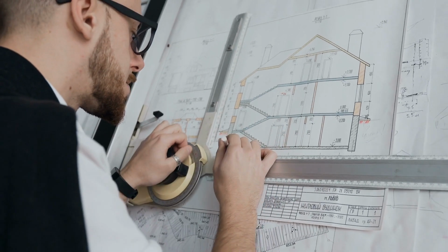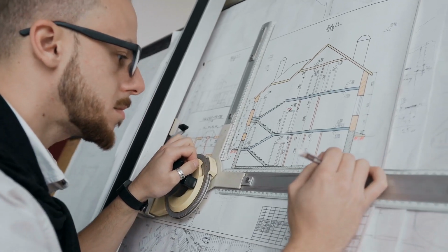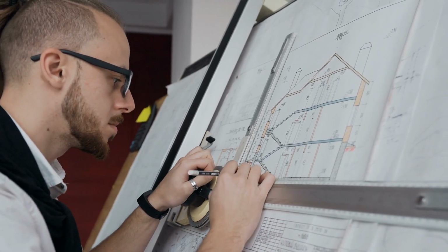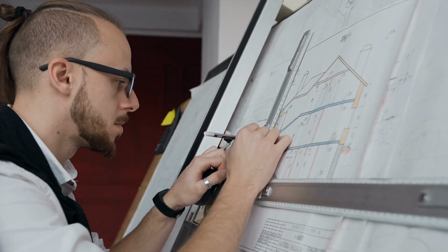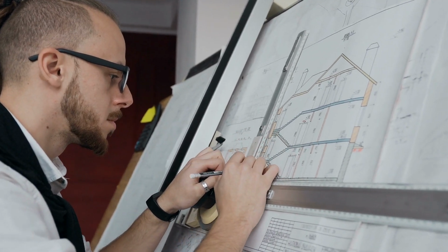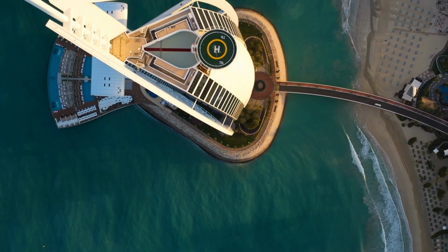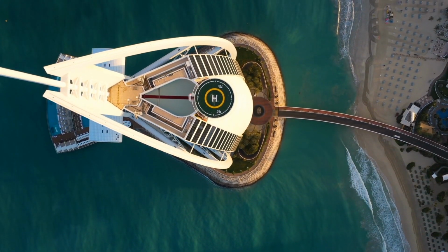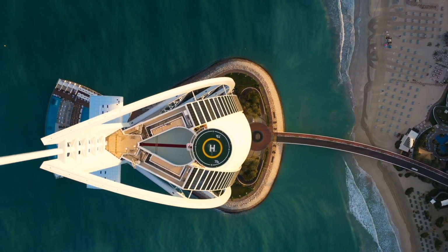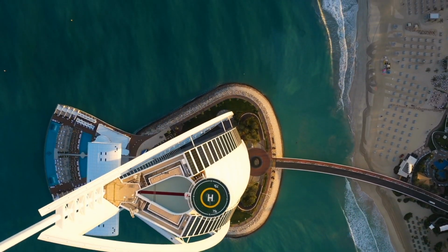Now that I've given you this overall information, it's time to dive into how we actually read construction drawings. I will be showing an example drawing soon that we'll look at in great detail, but before we do, let's talk about 4 specific viewpoints that are commonly found on a construction drawing. The first of these views is the plan view. Otherwise known as a bird's eye view, a plan view drawing is drawn from the perspective of looking downward from above at the finished work.